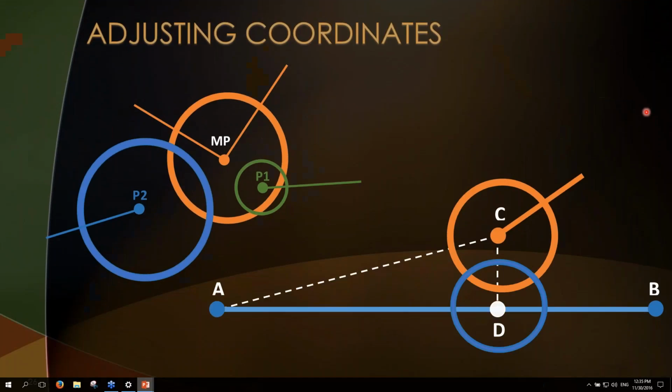So I designed an algorithm here for adjusting coordinates of endpoints of elements to create an integrated model. In this algorithm, these dots are showing endpoints of elements, a BIM column, shell element.